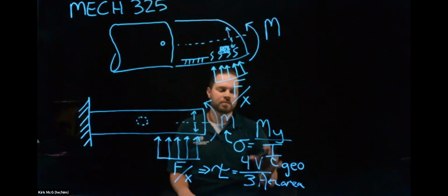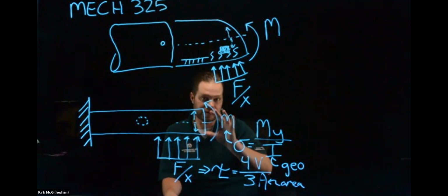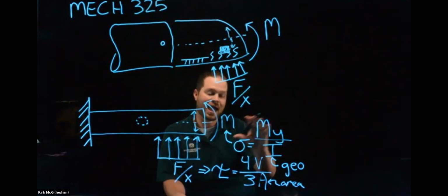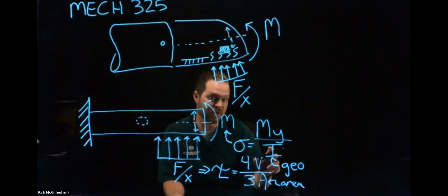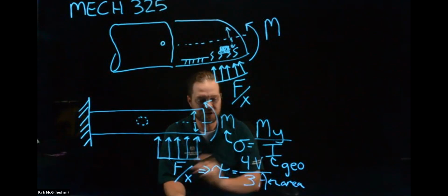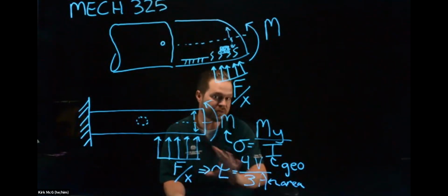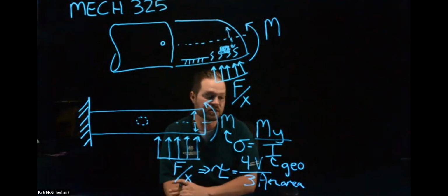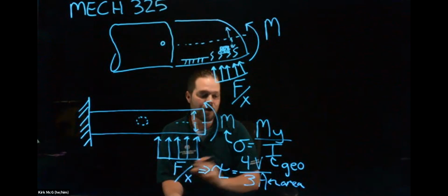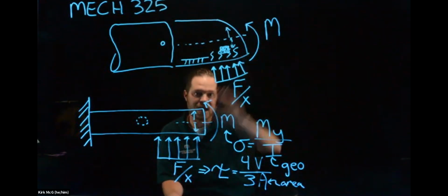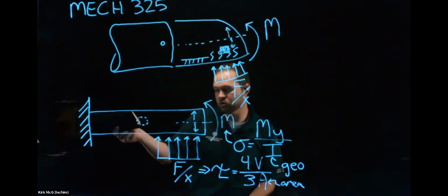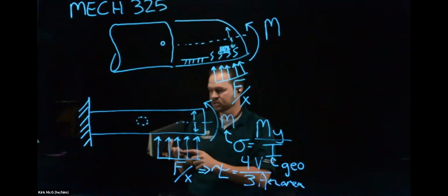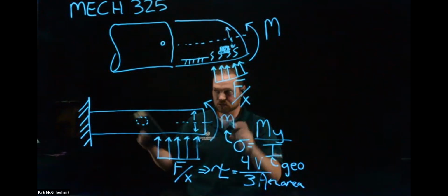All right, so let's take a moment here. Stresses in our part are a function of the applied moments or forces, and a function of the location where we are in our component, as well as geometric concerns, whether that be area or I parameters. This is called the moment of inertia. We won't get into the details of that, but basically this is where we play as mechanical engineers. It is our responsibility to understand these stresses and how they relate to geometry, our applied loads and boundary conditions. For example, this is a boundary condition, meaning I have fixed this in the wall. It's not allowed to rotate. It's my approximation for the finger here, okay? Is everyone following along? Yes, okay.